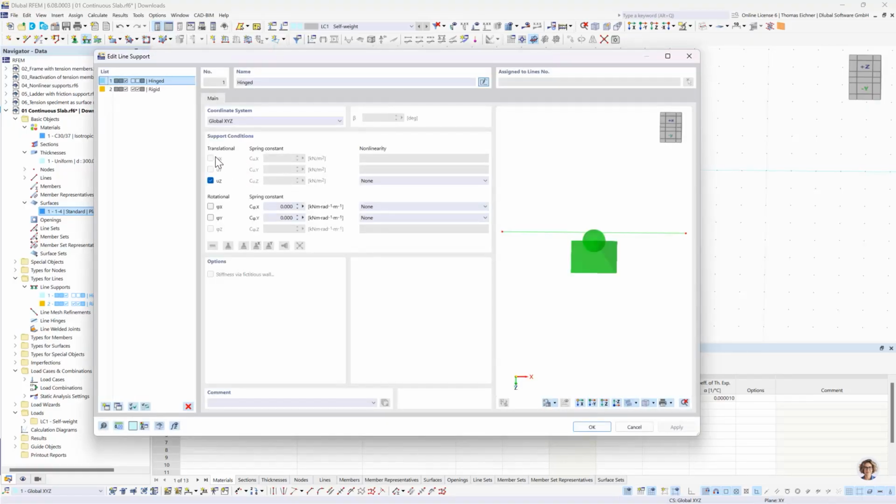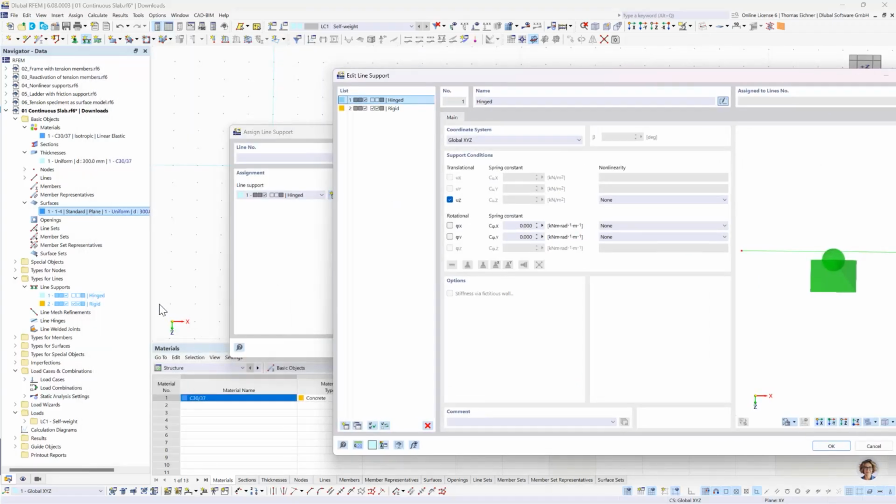And now we will see the benefit of our early decision to model it in the plate dimension and not in the 3D domain. And that's quite simple. The program now helps us since we are in 2D plate. We don't need the deformations in the horizontal directions anymore. And we don't need the rotation about the z-axis, which also would be kind of deformation in horizontal direction.